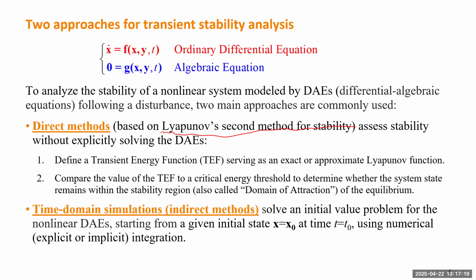The simulation needs to be run for a long enough period until you can clearly tell the system to be stable or unstable. If most variables have a very clear trend going back to the equilibrium or static condition, the system is stable. If any variable is flying away, you can stop there and give a judgment of transient instability.